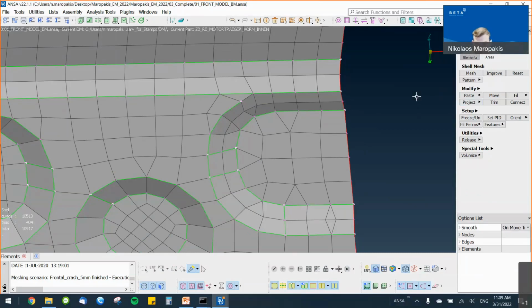When we have the direct edit functionality active and I hover my mouse over my model, I can see a preview of the action to be performed. This preview changes depending on the entity that I hover over. To have a clearer view of the direct functionality, we have the function assistant or the information window on the bottom left corner of my window that I can activate by clicking this eye.